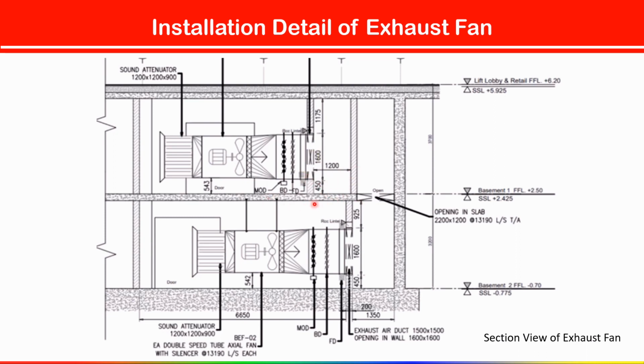This is a section view of the exhaust fan. See, we have to maintain a 1.2 meter distance from this wall up to here. Then we have to hang this exhaust fan, and the minimum distance we have to maintain from the finished floor level to this fan is 543 mm. You can see here we have different components inside this fan. This is our fan. Now here we have a motorized damper. Why are we using this damper? To regulate the speed of our fan.